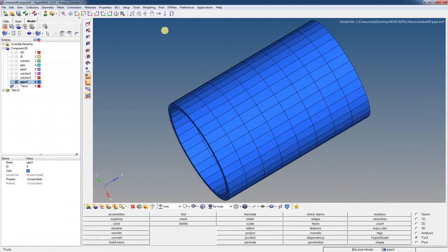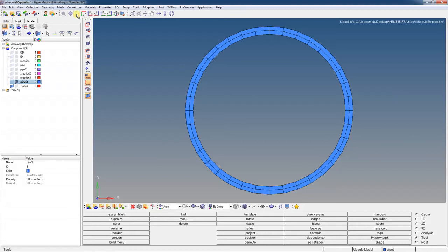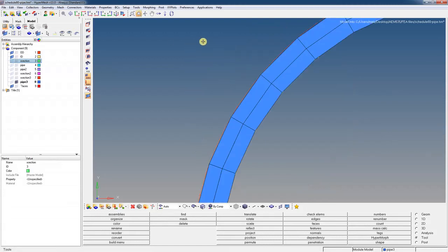Now what I'm going to do is give you this mesh. We're going to worry about mesh creation a little bit later. There are some things you want to be careful about when you create finite element meshes. But for now, this is going to be okay. But I do want to point out that even now we have kind of an approximate version of what our pipe really looks like. If I were to show you these lines for the ID and the OD, let's kind of zoom in on it. We're using what are called first order solid brick elements.